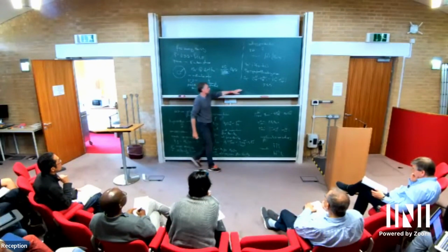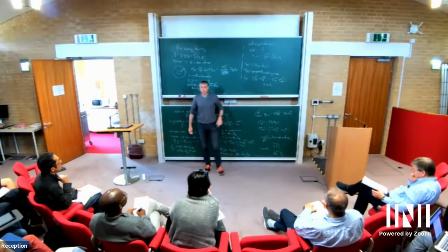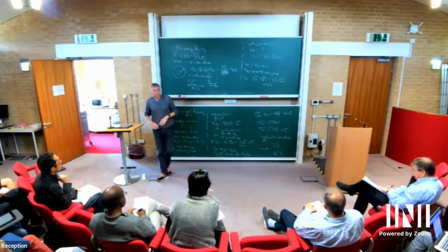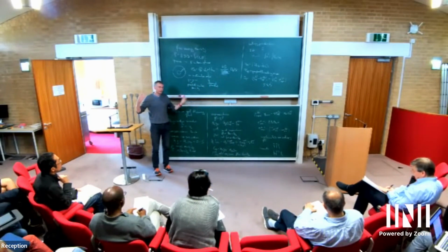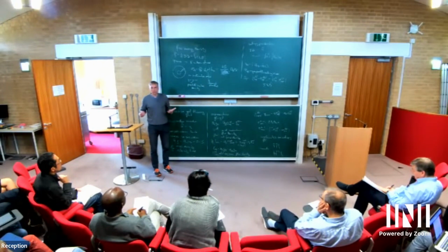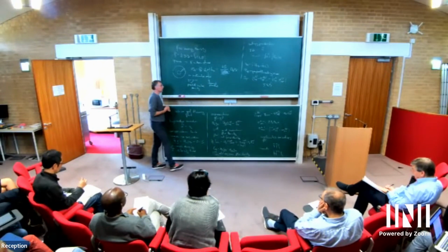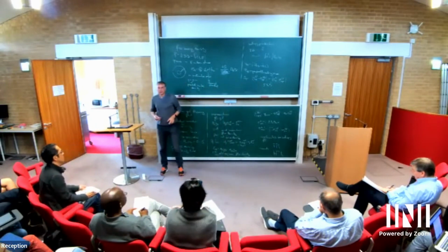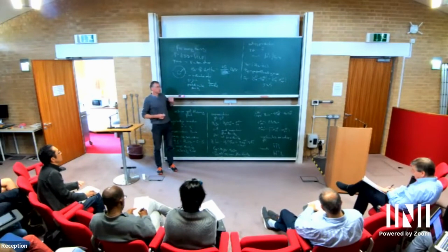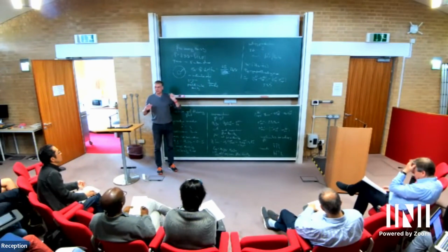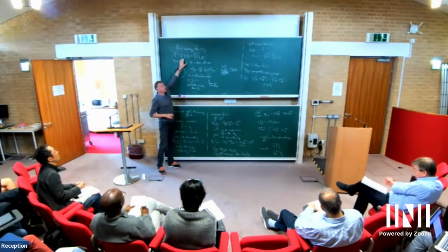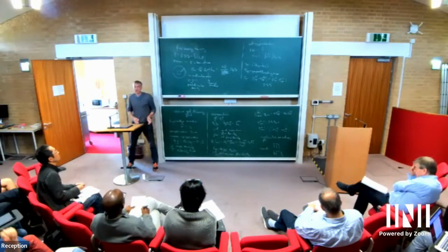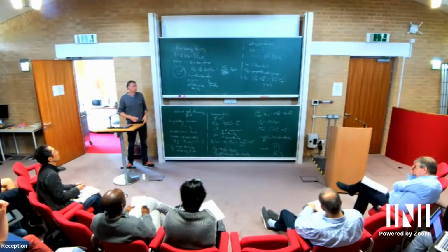This later we will neglect in any case, because a large portion of biological flows happen at low Reynolds number. So this will vanish in some place in any case. I cannot do the derivation though by starting in the low Reynolds number case. I always have to first consider the kinetic energy and then afterwards go to the limit where I can neglect that.